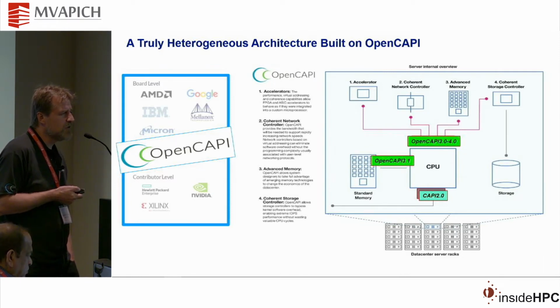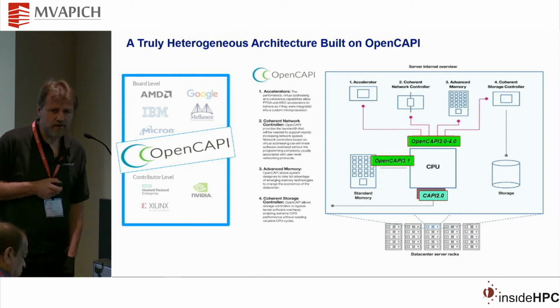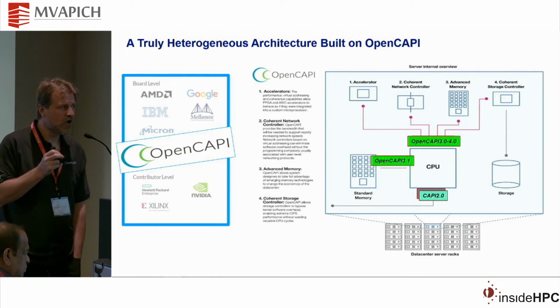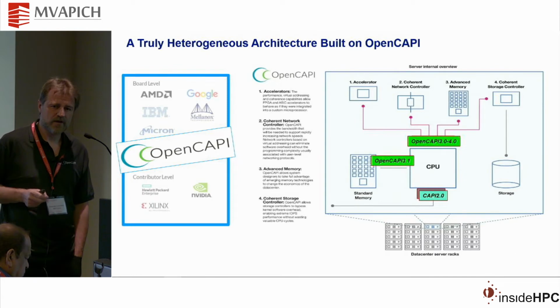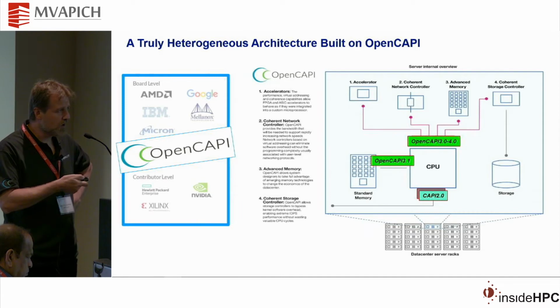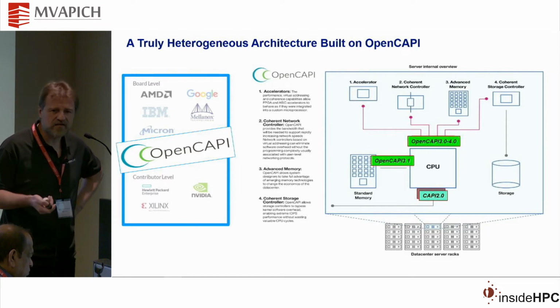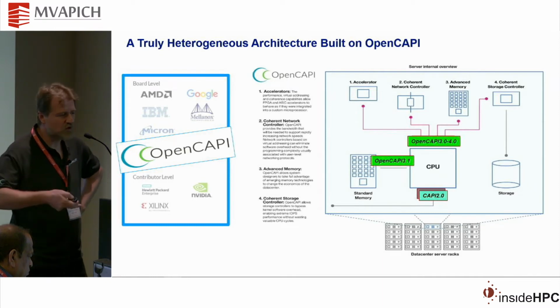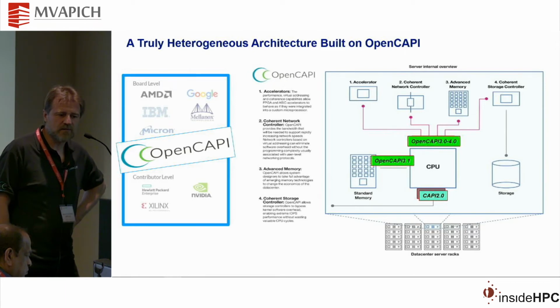And standard memory will have a specific version of OpenCAPI 3, which will be named OpenCAPI 3.1. It might be a little bit confusing, but 3.1 being a tuned version of CAPI specifically dedicated for standard class memories, okay, to have a very low latency, and it's really aimed at being hooked up to memory. So the main CAPI we speak about today is CAPI 1 and 2, eventually CAPI 1 for training purpose, CAPI 2 for easy access with existing boards, no pain, plug the board, it works, and eventually very advanced and very fast solutions using OpenCAPI specific hardware.